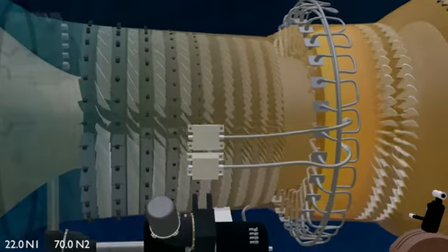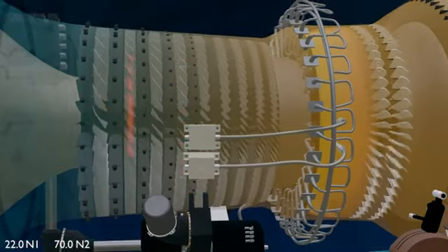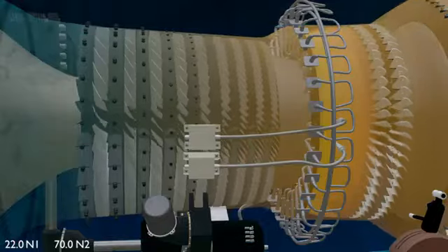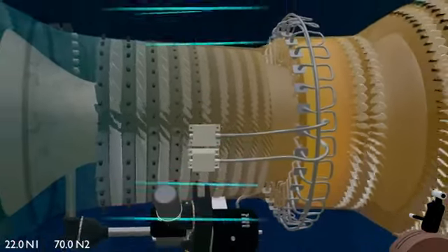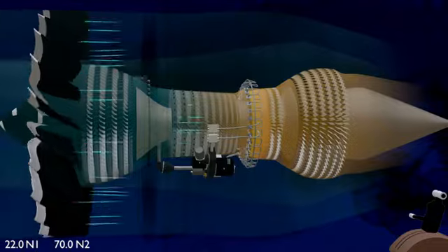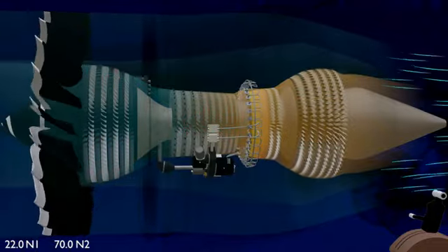Pockets of such inefficiently compressed stall cells start to form throughout the compressor stages, thereby reducing the efficiency of the high-pressure compressors. Poor performance of HPC stages overloads the low-pressure compressors due to airflow mismatch, which can lead to compressor surging and eventually engine damage.